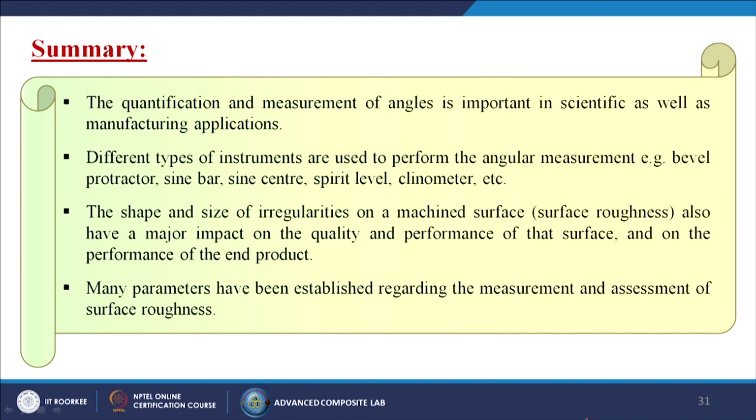The shape and size of irregularities on a machined surface, like surface roughness, also have a major impact on the quality and performance of that particular surface and on the performance of the end product. Many parameters have been established regarding the measurement and assessment of surface roughness, and as I told already, nowadays we are using the optical profilometer or AFM, atomic force microscopy, by which we can get more and more accurate, precise surface roughness values of your surface.